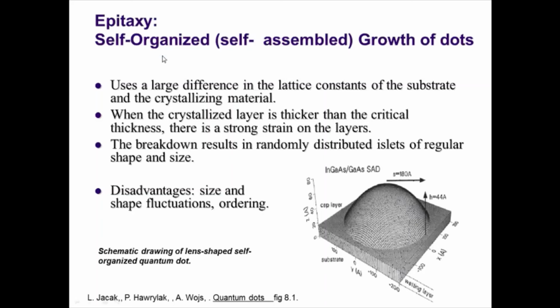This is because of the large difference in the lattice constant or lattice parameter between the substrate and the epitaxial layer being grown on the substrate. So you have a large amount of mismatch occurring at the interface. Because of the large mismatch, large stress or strain comes into the picture, and this stress or strain is released in the form of buckling at various places on the substrate. And this buckling comes into picture only when the capping layer or initial layer grown on the substrate is less than the critical thickness. So this condition you have to remember.